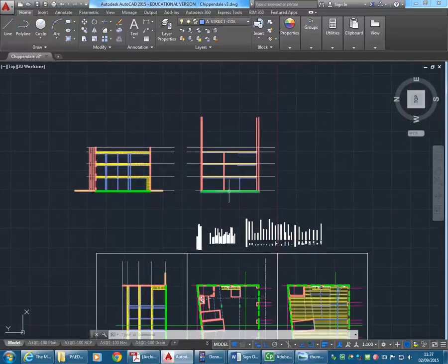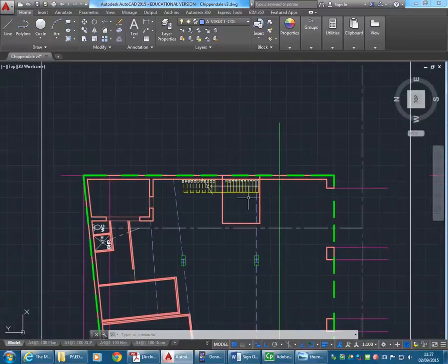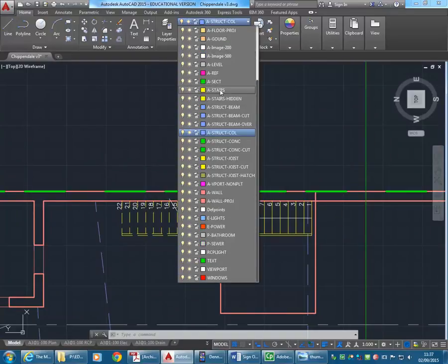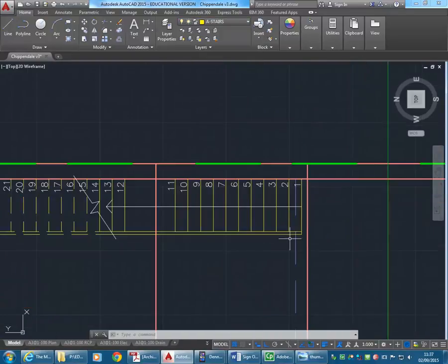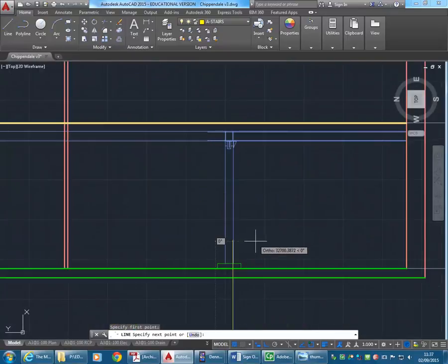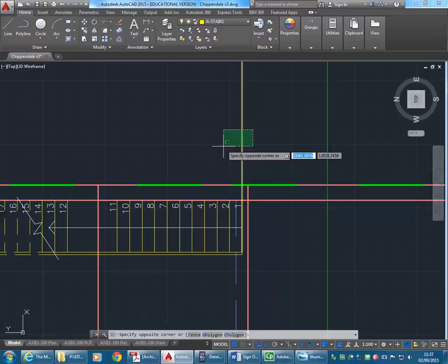And the same with things like stairs. So maybe just to get you started with that, because that can be a little bit more fiddly. But again, once you see how it's done, it's really not that difficult. So always with stairs, think about the rises and the treads. So when you draw them, if you're thinking about those things, starting here with the front of that tread there and projecting up to the floor plan, it's going to be behind the column, but we'll see most of it on the left of that. So I'll just copy that line across a couple of times.